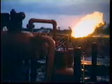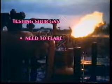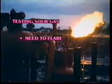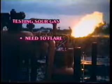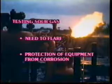For testing sour gas wells, even more equipment is needed. In addition to that mentioned above, a gas meter and flow line to an appropriate flare stack is required. In Alberta, for example, if the gas contains over 1% H2S, it must be flared from a stack at least 12 meters high, and flaring must take place at least 25 meters from the wellhead. Liquid seals may also be needed to protect the gas meter and deadweight tester from the H2S gas. Other measures to protect against the corrosive nature of the gas might need to be taken.